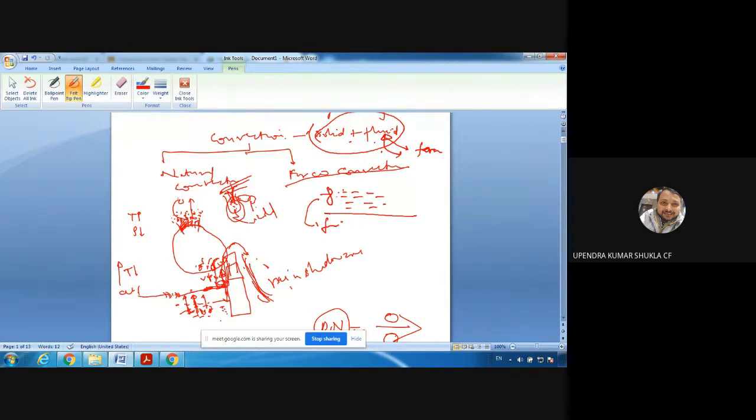So heat transfer in natural convection is more complex to analyze than forced convection. The reason is that if we are using a fan, we know the velocity profile of this fluid a priori. But in natural convection, since the fluid motion is caused by temperature difference, we don't have any idea a priori for the velocity.